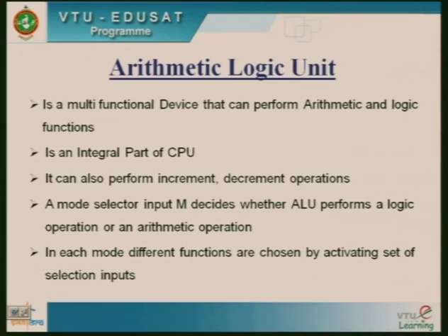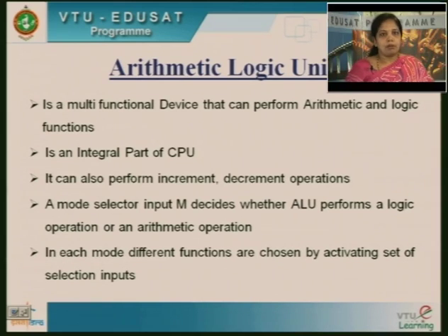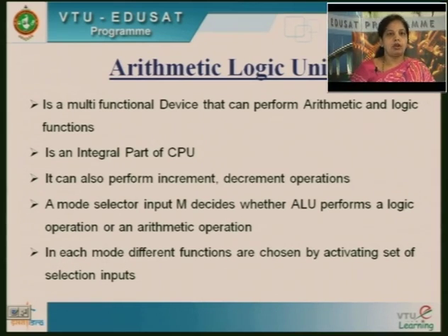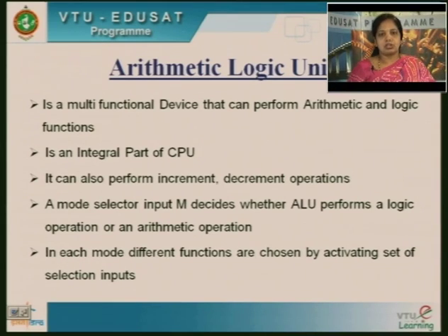It can also perform increment and decrement operations, and there will be a mode selector which decides what kind of operation I want to perform, an arithmetic operation or a logical operation. In each mode, different functions are chosen by activating selection inputs.